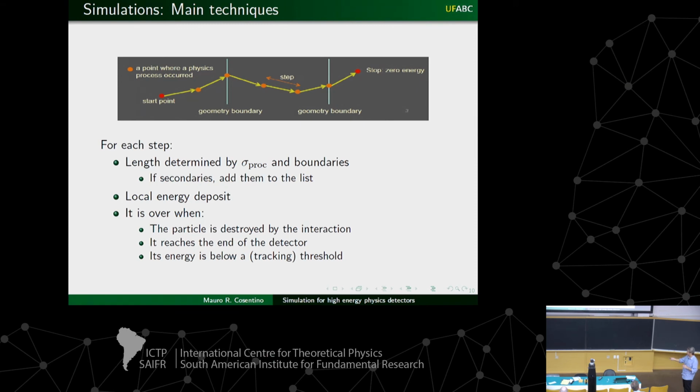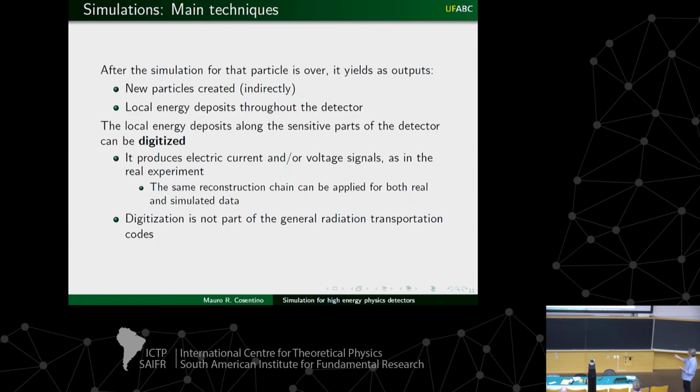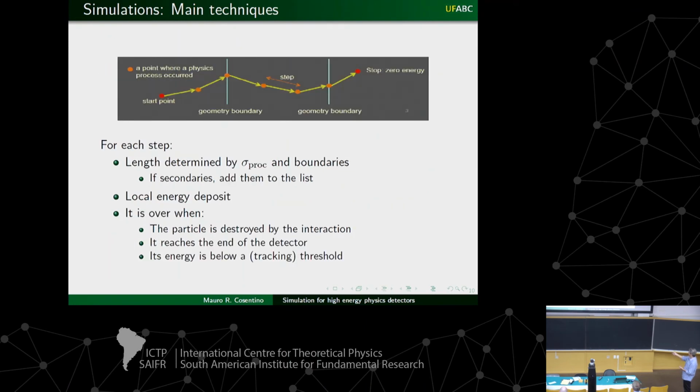If you set this threshold at some energy higher than, for example, 1.2 MeV, then you may not see pair creations at lower energies. You may see a pair creation if you have a photon of 20 GeV, but you may not see any pair creation below, I don't know, 100 MeV. This is useful because sometimes you want to make a fast simulation, but of course your response will not be very realistic, right? So we have to be careful when tuning this.